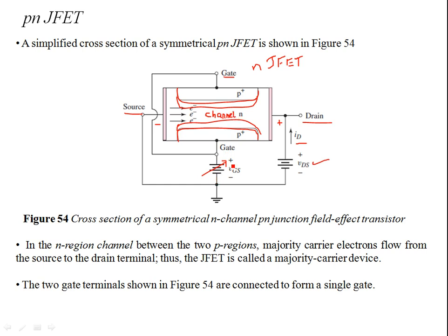That is, if you apply the gate source voltage such that it reverse biases this PN junction, formed from the P-type doped regions with the N-type substrate, and the reverse biasing increases so much that it is choking the channel, then there is no current. We call this the very famous pinch off voltage. So you've pinched off the channel, and there is no current even with increasing VDS.